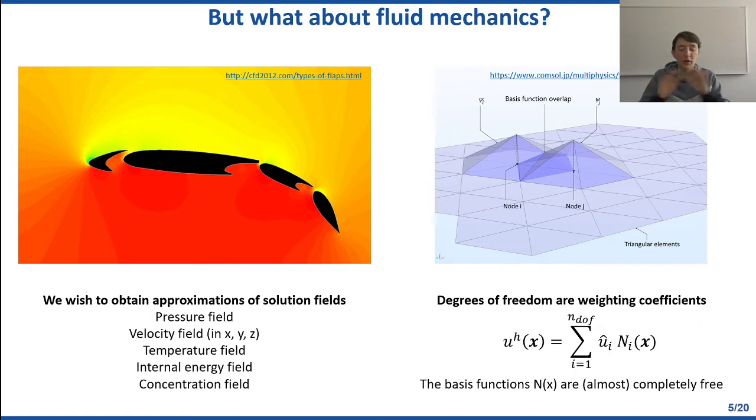And then we can represent a whole bunch of different functions. So that's what's shown here on the right. U is this sum over the number of degrees of freedom of coefficients times functions. And these functions are based around this tessellation of our geometry by a mesh of elements, and that's where they are defined. But in principle, they could be anything. You could use trigonometric functions here, and you would get a spectral method. You might have functions that have very global support. That's what we see with reduced basis methods that we talk about in the model reduction course.